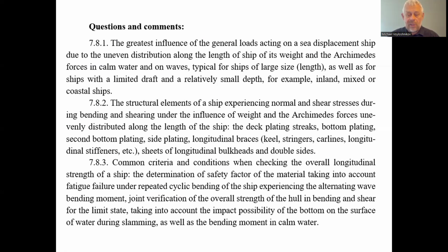Exactly for a ship of big length and small depth, considering the most critical loading, the general loading, general shearing forces and bending moment, these are the most important elements of the ship withstanding the general load under the weight and under the buoyancy forces on behalf of water.